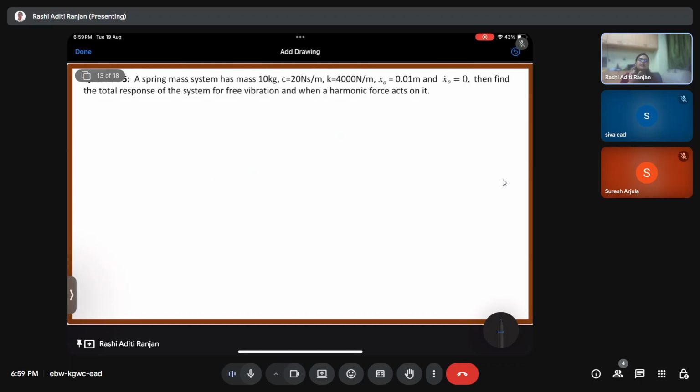Okay, it is applicable only for the linear range. If we are considering a system where the deformation is more than 3% or 4%, for that we have to now consider the nonlinear equations. This is applicable for a system where the deformation is around 3% or 4% of the length of the system, or whatever the dimension in which the deformation is happening.